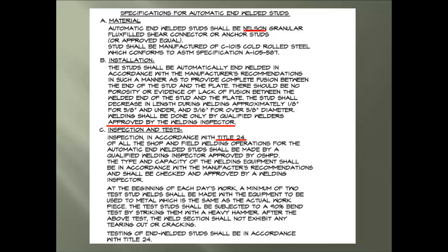Here is the way the California Building Code is addressed at times, Title 24. We see OSHPD is the jurisdiction having authority for this project. Here is the required testing for daily production of welded studs. So I ask, are these instructions for testing more or less stringent than the code? Why, you may ask? We see how testing must be in accordance with Title 24.